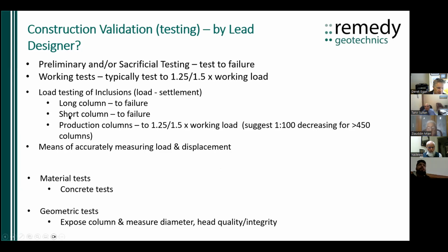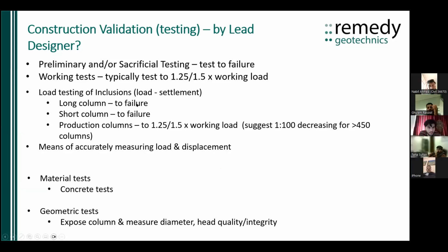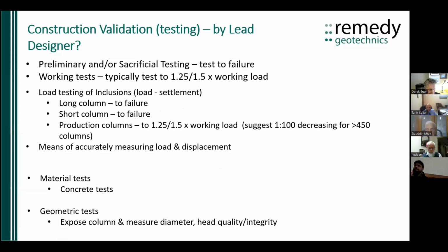They could be very valuable. And then your long column, when you test that, you've got to allow for the working load that's going to be applied, and you've got to then add on to your load in the test the resistance that's been generated within the test over the negative skin friction length, to ensure you really are testing the bottom of the column to the maximum load it can be exposed to.